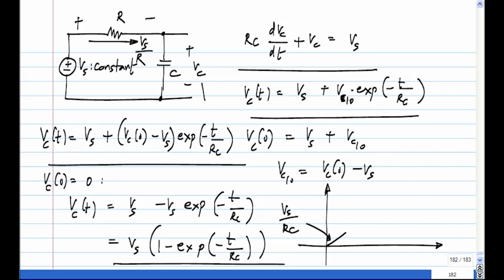If you differentiate it, do you get that? At the initial instant, you do get that, right? So you get plus Vs by Rc. So that sanity check is also satisfied. But as the capacitor voltage increases, what happens to the current? It decreases. Because this voltage is ramping up, the current will reduce. So that means that the rate of increase of voltage falls.